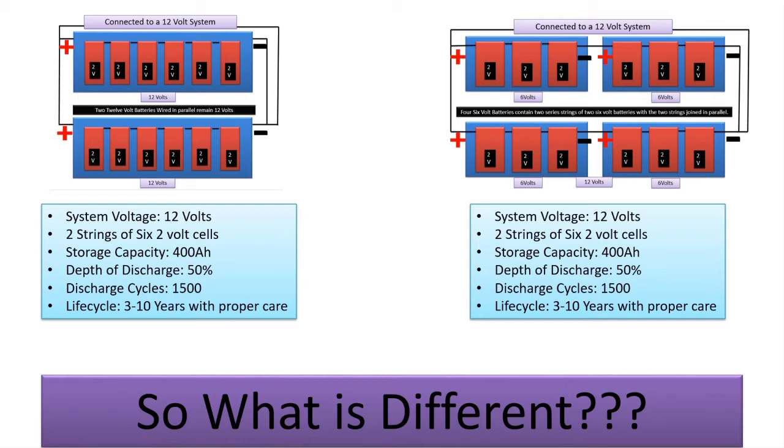There are many good brands of AGM batteries. T105 Trojans, the AGM version. Full River DC 224-6 are 2 6-volt batteries that are viable choices. Based on my research, I'm choosing to purchase 2 12-volt Odyssey PC 1800-FT batteries. The primary driver for my choice is that Odyssey battery claims to have the fastest charging AGM batteries, a claim that's supported by field experience of RVers and van dwellers that I've personally been in contact with. One user in particular has over 4 years on his set of 2 and is going strong.